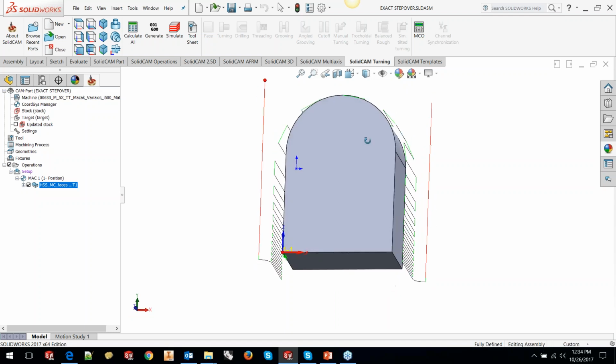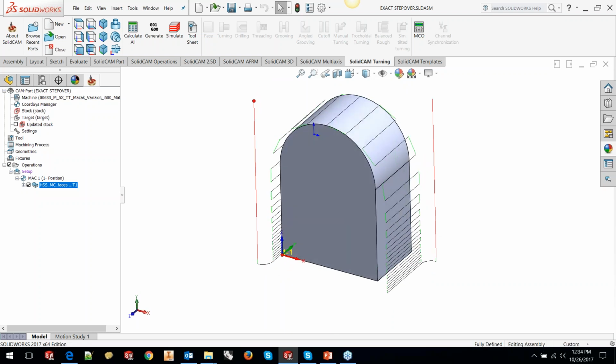The problem here is we used these two curves as our morph curves. So what HSS does is it internally creates a surface between those two curves and then unflattens the outside area to project the cuts that are there on this small surface.